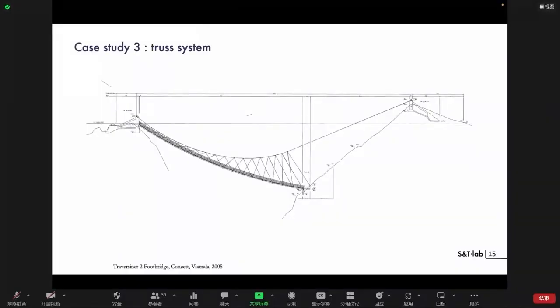This arrangement allowed Conzet to use the ribs on either side of the valley as natural pylons for a suspension bridge, and the bridge accommodates two drastically different elevations. And at the end, the bridge acts as a massive cross-laminated timber staircase suspended with cables. So at the end, the span is 57 meters and not 100 meters with this methodology.